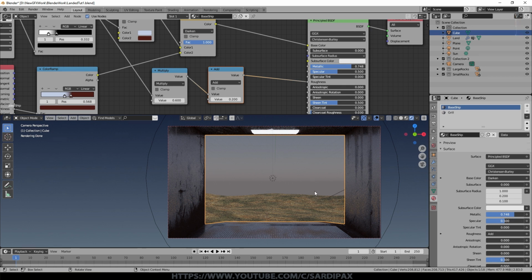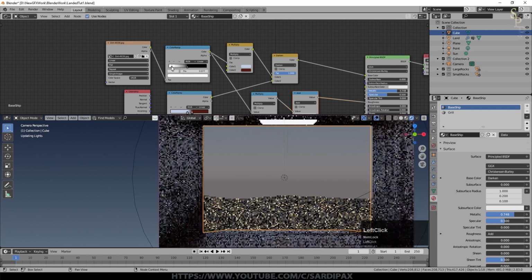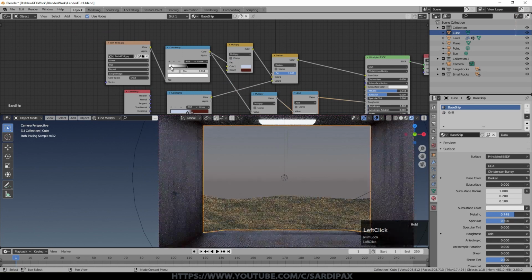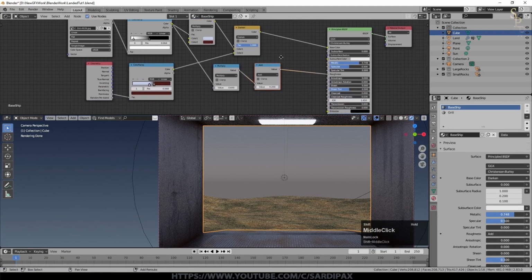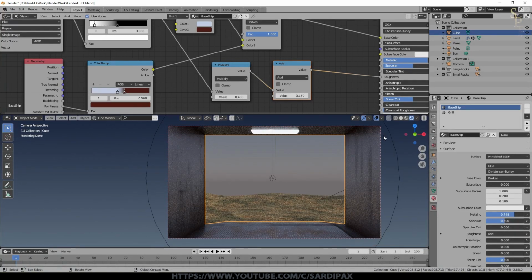So we can see a little bit of the color of the landscape reflected out there, but not too much, but very little of these grimy bits. Now, if that's a bit too extreme, we can obviously ease that off by taking that out to here. So just moving this little slider, and that's reduced the effect of the dirt slightly. And I'm just scaling it back a bit because I changed that. I'll go with 0.15 now. So that's that. That's the basic material for the ship.